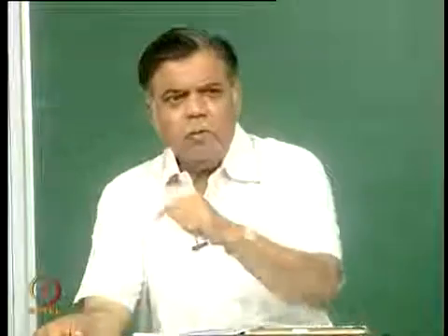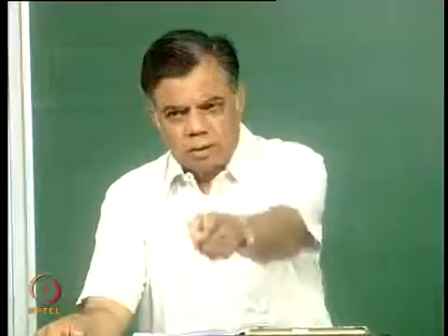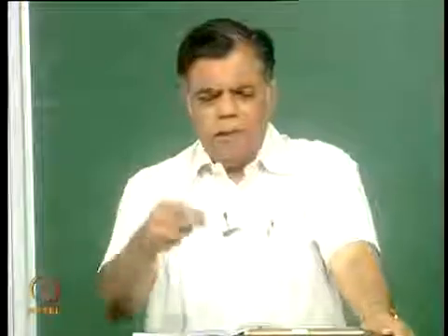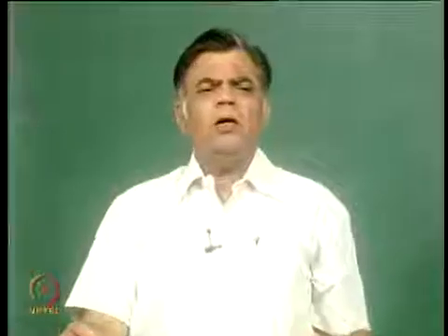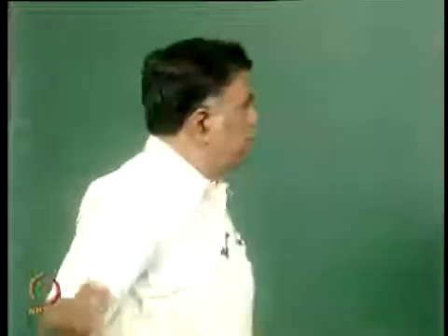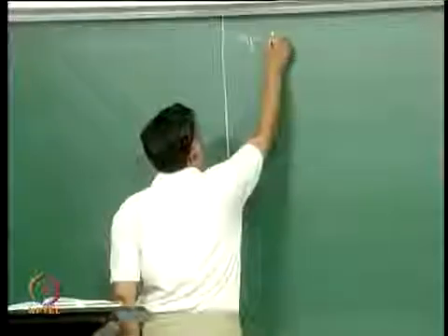So now, to save time, you are integrating the PDE, you have to integrate. Now you do that here, that is what I am saying. d square u by dy square, twice you have to integrate, and of the 2 constants, the 2 boundary conditions you must have at y equal to 0 and y equal to L. Please, by looking at the equation you should be able to write it, it is nothing but u by u1 is equal to, so now we will go to the next step, step 4, solution.